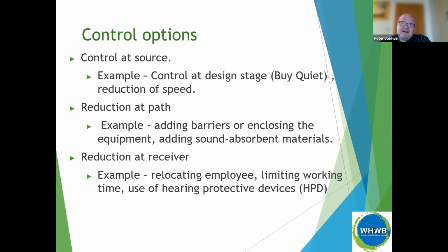So we can get around that by putting in some absorbent materials, so the noise is absorbed, to reduce its transmission path. That could also be a case of treating reflective surfaces, because noise does get reflected off hard surfaces. If you make the surface soft by putting these absorbent materials on, you stop that retransmission and that reflected noise.